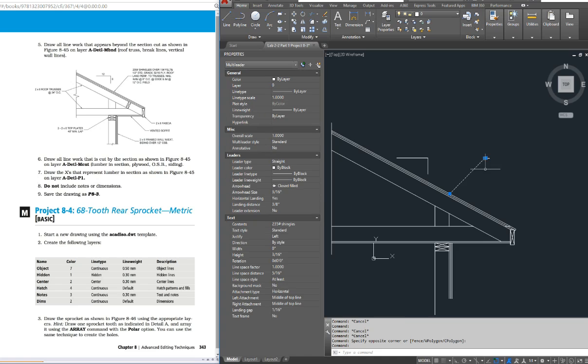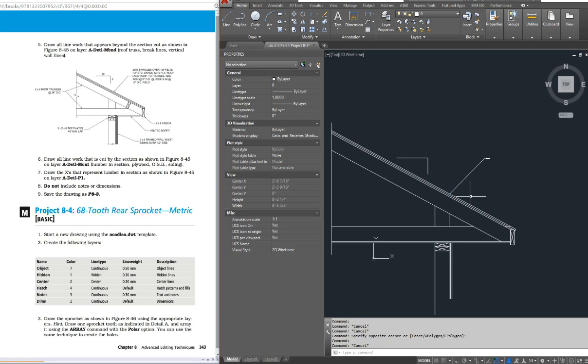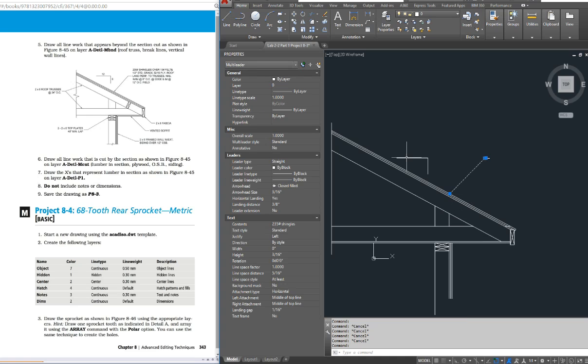So once you're finished, you can either set your text size before you create it in your dimension style, or you just select it, come over here and look through them for the arrow size. Maybe let's change, you can't see the arrow right here. So click on that again. Come down here, you can change the arrow size, let's say to 4. That's pretty big. How about 2? That looks pretty good.